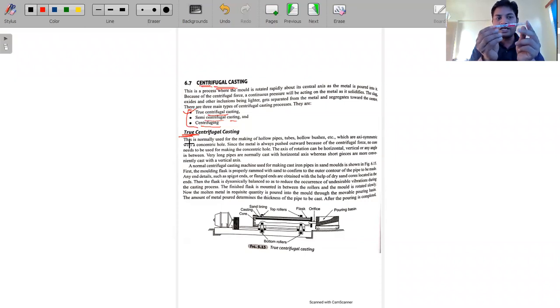So accordingly, whatever the length and diameter of the pipe that we have to produce, we use the pattern of that pipe, and we rotate it when we fill, adding the material continuously. First it will fill some specific thickness, and then this thickness increases from the outside periphery.